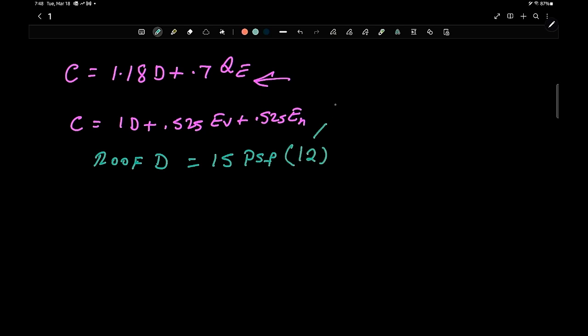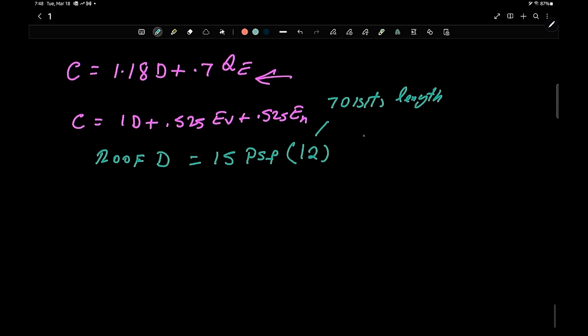This is the joist. And then our wall was a 10 feet shear wall. The tributary dead load to the tension chord was half of that, which was 5 feet. So we're going to divide that by 2. And this should give us 6 times 15 becomes 90 pound per foot.